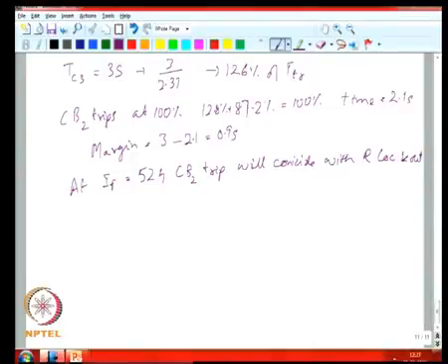So, if your current level is above say 524 amps, then your CB2 would trip before the recloser operates, locks out. So, if you set your threshold current level for your recloser to be higher than 524 amps, then the recloser would not operate at the reduced current level, ensuring that you do not have nuisance trips upstream because of reduced fault current levels that are occurring downstream. Okay.